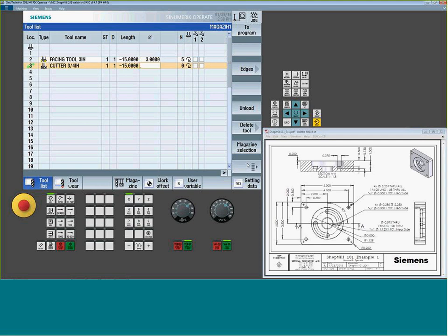It's going to give the system my tool diameter. Now, you want to pay attention to the symbol on the top of the page. If this doesn't have a diameter symbol, this could be radial. So it's really a machine parameter. It's up to the builder whether he wants to set them up to be a radius value or a diametric value. This one's set up for diameter. How many flutes? I'm going to do 3. Whether I want my coolant, my direction. And you see I get no further data. It means I'm done. There's no other information I need to worry about at this point. We select the To Program button.